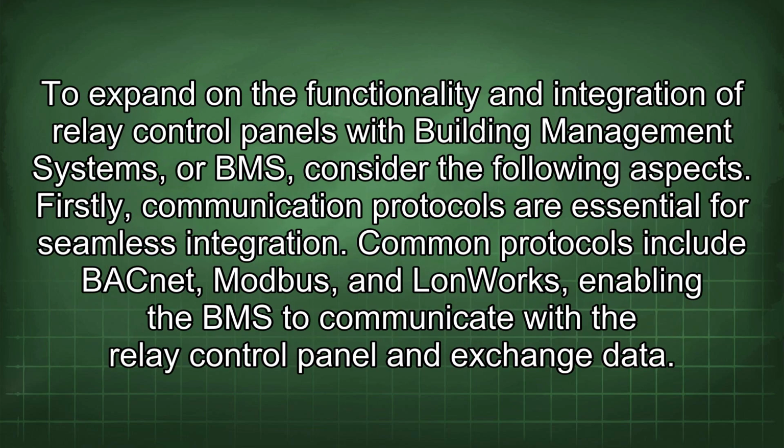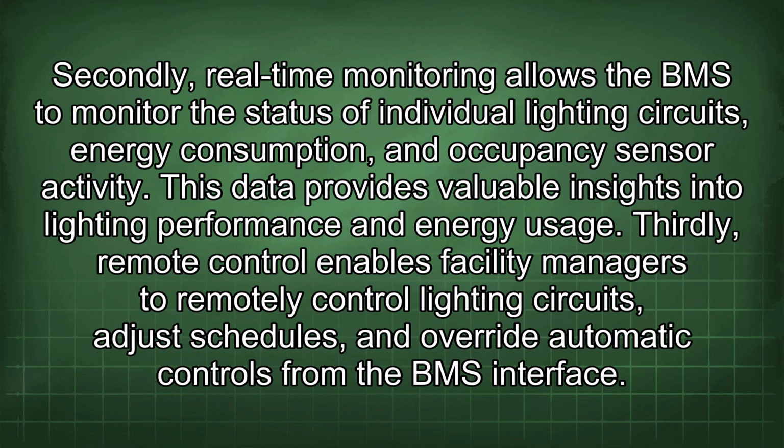To expand on the functionality and integration of relay control panels with building management systems, or BMS, consider the following aspects. Firstly, communication protocols are essential for seamless integration. Common protocols include BACnet, Modbus, and LONWorks, enabling the BMS to communicate with the relay control panel and exchange data. Secondly, real-time monitoring allows the BMS to monitor the status of individual lighting circuits, energy consumption, and occupancy sensor activity. This data provides valuable insights into lighting performance and energy usage.